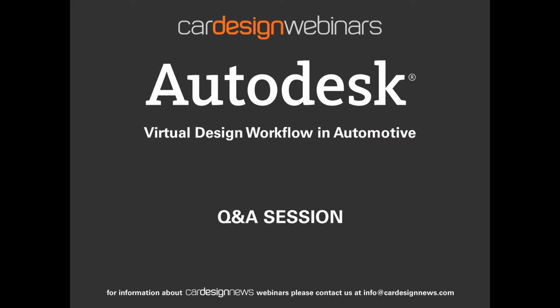Thank you. One more here is, how does patch layout for Class A surfacing differ from quick conceptual surfacing in Alias? When you do quick conceptual surfacing, you have the idea in your mind, and you even get paid for that. Your design boss pays you for developing an idea. When you are a universal genius who is already capable of thinking about engineering or legal requirements, that's fine. But I think as a concept modeler you should concentrate on the concept, while a NURBS modeler who is particularly concentrated on a patch layout that fits engineering requirements, highlight quality, and all this kind of stuff will have a different one.